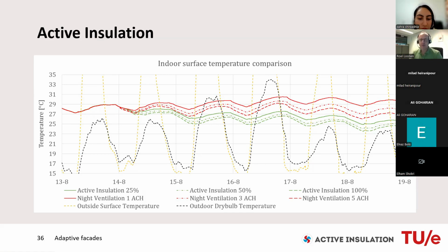With this system, we can really help to cool that down and to have a maintained effect that is present over a couple of days, while with the ability to open the window, you can quickly flush out the air, but once it gets warm again, it quickly heats up, actually. So it doesn't really last, unlike this active insulation approach. And we have found this out with the use of simulations in EnergyPlus to really investigate such effects in detail.